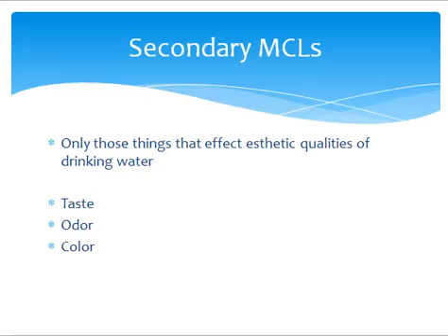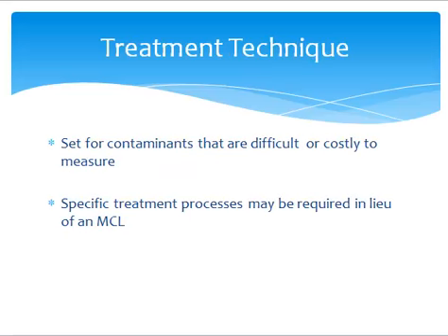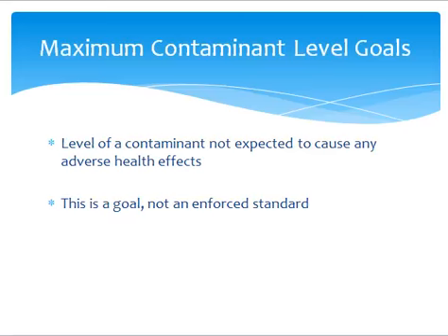Secondary MCLs deal with the aesthetics of water, such as taste, odor, and color. Although there are national standards, states or cities may choose to set more strict secondary MCLs. When a contaminant is difficult or costly to measure, the treatment technique may be dictated as opposed to the MCL. Maximum contaminant level goals, or MCLGs, are just that, goals. However, for known carcinogens, the MCLG is always set to 0.